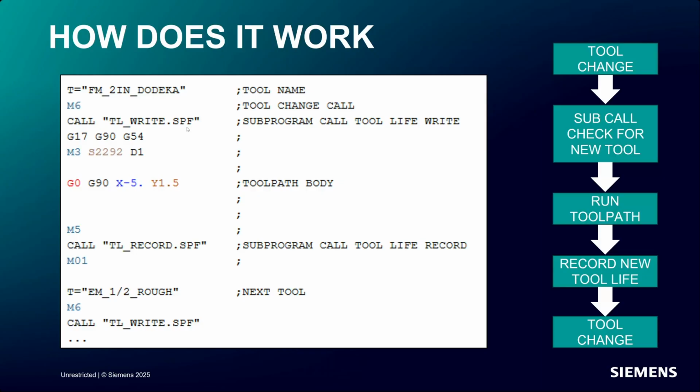The next thing it's going to ask is, is this a new tool? And if it is a new tool, has that tool been run before? If all 3 of these are yes, then it will write the data that is stored in the global variable. I wrote that last question, has the tool been run before, to keep you from getting brand new tools that you write. The first time you put this program in there, the first time you create this tool, it hasn't been run before.